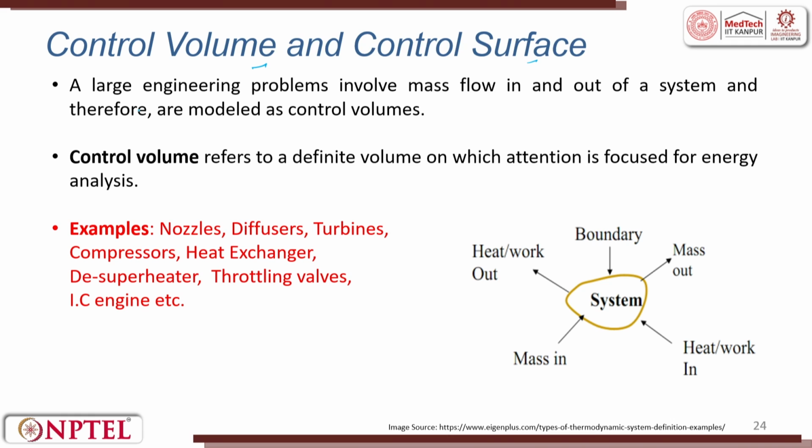Okay. A control volume and a control surface. A large engineering problem involves mass flow in and out of the system and therefore is modeled as a control volume. Any engineering system will always be modeled as a control volume system. A control volume refers to a defined volume on which attention is focused for energy analysis. So, you have a system, there is a boundary, there is a mass in, there is a mass out, then there is a heat in, there is a heat out. So, this is a system, and we call it a control volume.